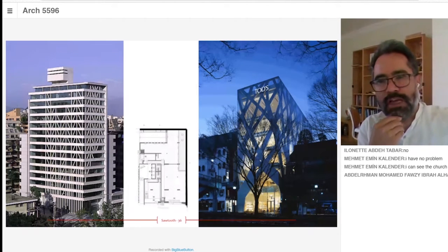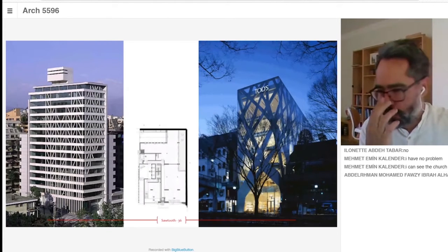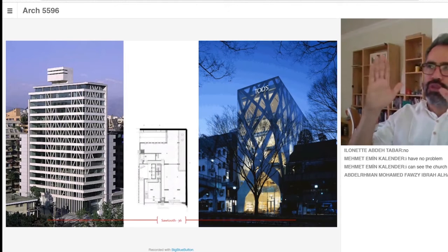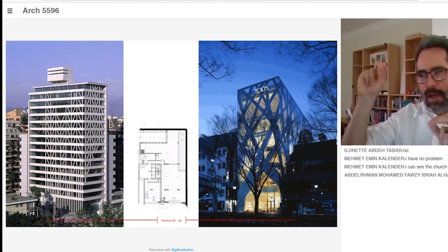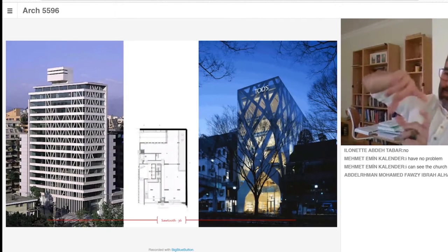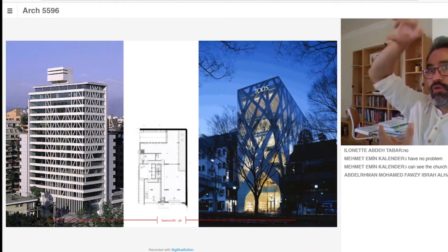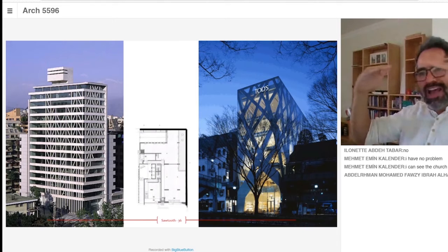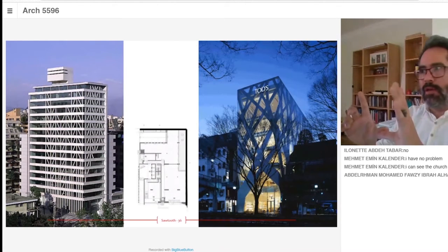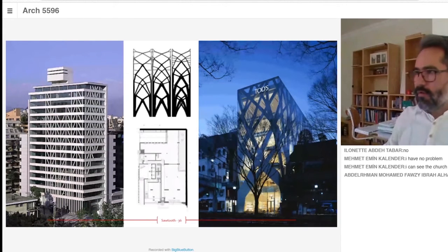But I would say, in topology optimization, which is a technique that allows you to distribute the material according to the loading you are going to have, if you take a rectangular surface and you put it vertical, and then you apply lateral forces, as happens in an earthquake, or at least the simplification we make of it, then you're going to have a distribution of forces very close to this that I'm showing you now.